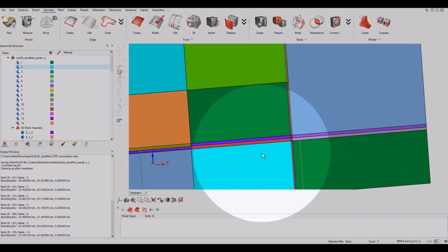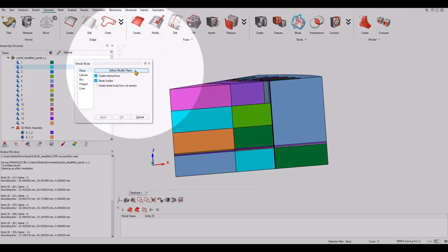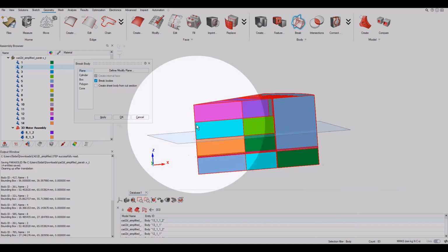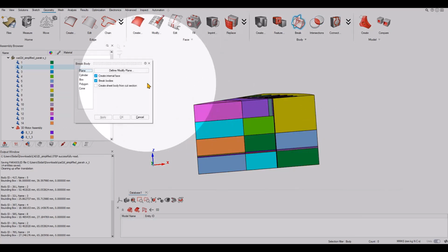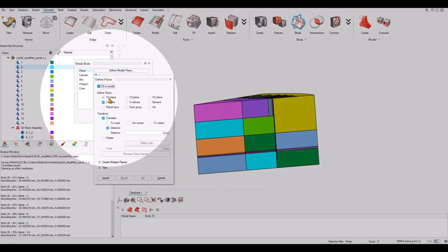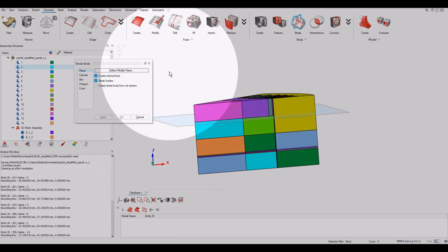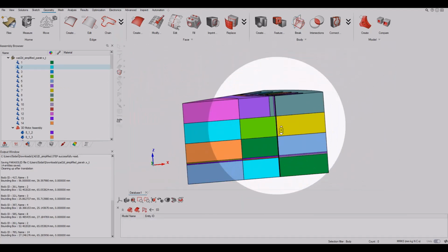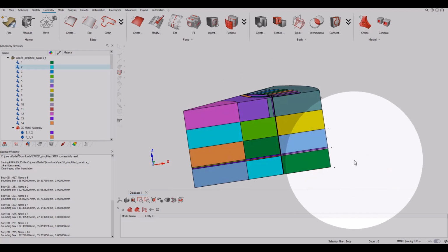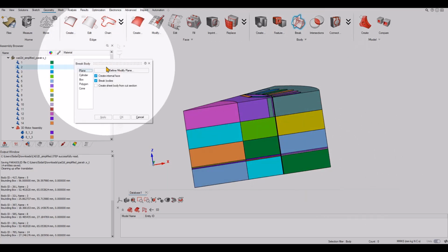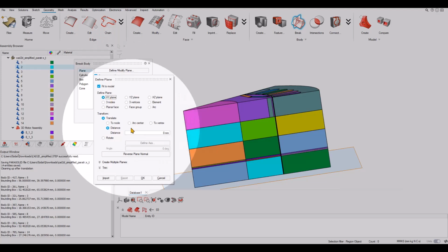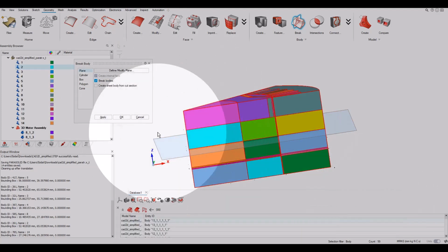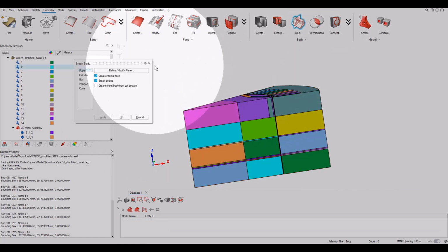So actually, in addition to the physical behavior, I want to consider these additional layers where I will add additional mesh elements. Later, when we have extrusive mesh in 2025.1, we can make extrusive mesh as well on each layer. So then I continue the creation of the cuts in the same way.